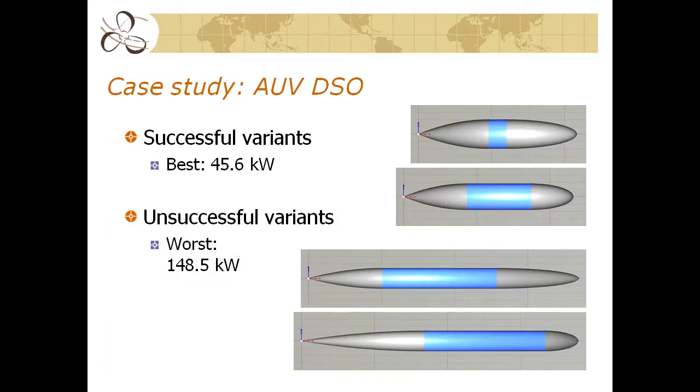And what we found was that for the 4-knot case, the larger diameter, shorter vehicles proved to be substantially superior to longer, narrower ones. Now, from a straight resistance standpoint, they might not have been, but because our propeller design constraint was that we allowed the propeller diameter to grow to within the limits of the body diameter, within a margin of that, we got so much better on the propulsor side that we could give up certain resistance losses because our system is better. And again, it was an overall duty profile based approach to things.